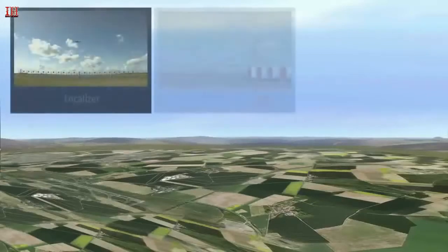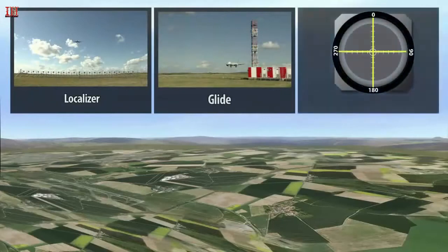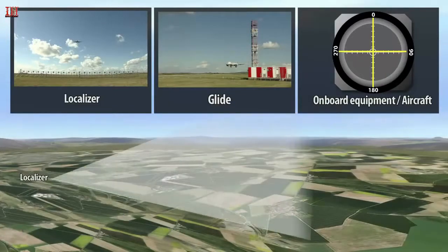The ILS system uses a combination of two independent subsystems, one composed of antennas located on the ground and one on board the airplanes. On the ground, the localizer antenna, situated at the end of the runway, transmits a radio beam that indicates the runway center line.